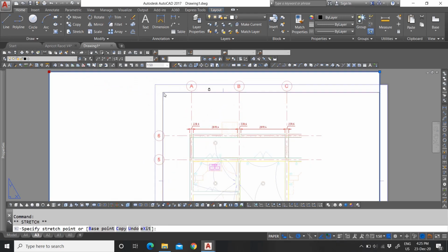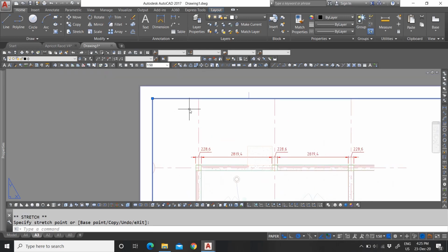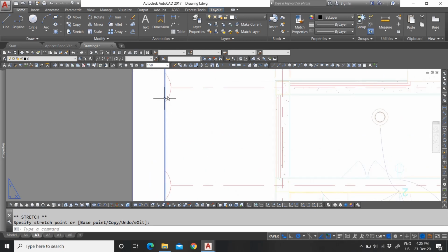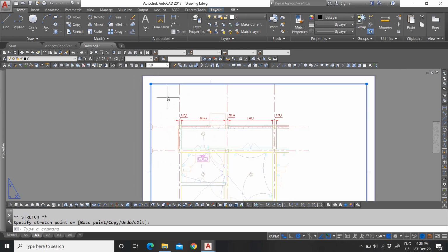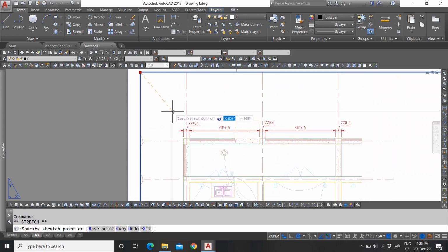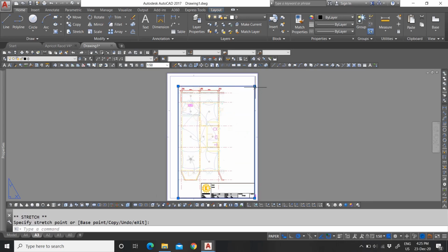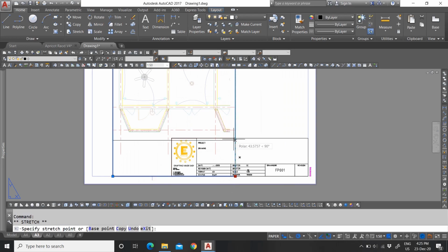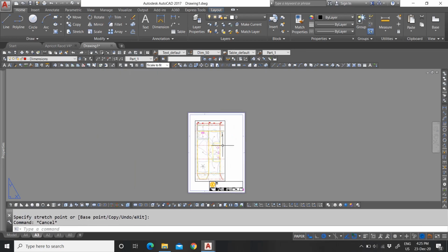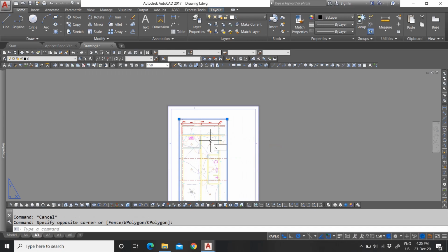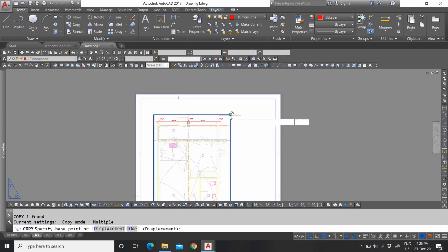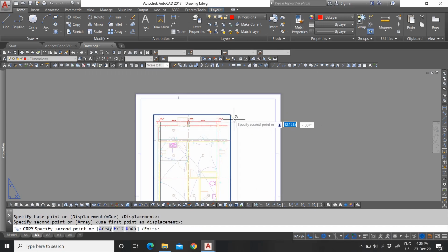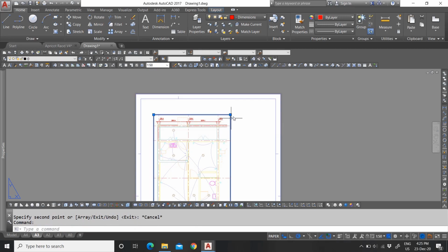So as you already saw, my grid lines or my grid balls are out of my drawing. That is not a problem. That's a good thing about AutoCAD and viewports. You can just easily close it up. So it will be nice and neat. And then you just copy paste your viewport in a corner and paste it in the same corner 2 times because we have two grids.